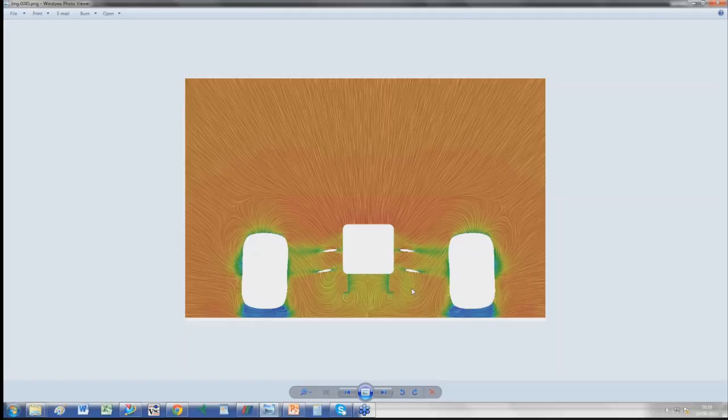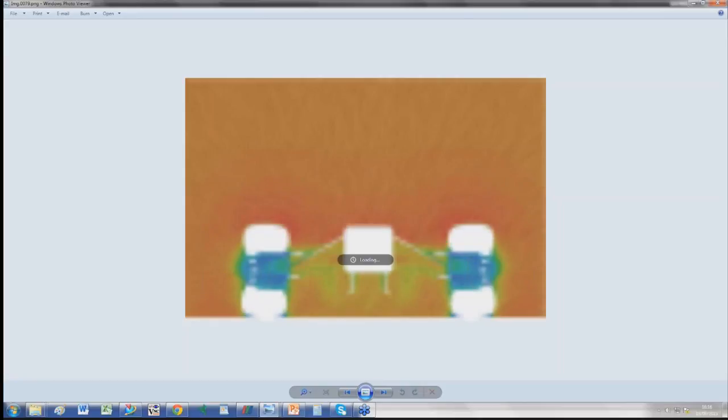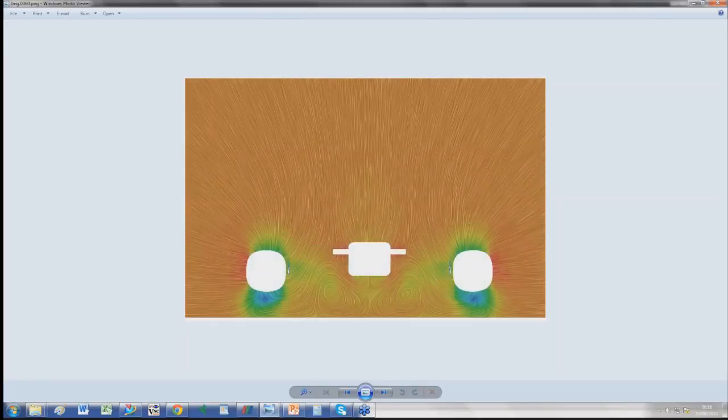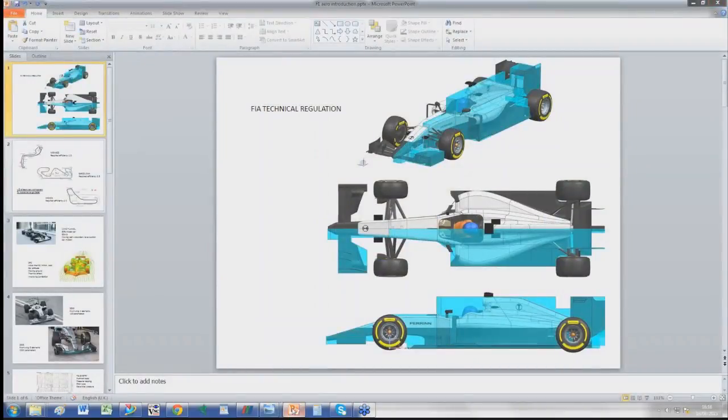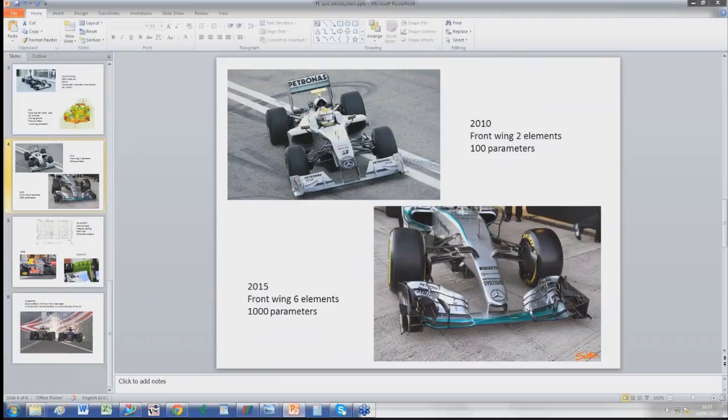to improve. And it's very clear that we need to develop the front wing much more to make this vortex stronger. It will mean that we need to crank or put more camber on the front wing in this area. So if I come back to my Mercedes comparison, it would mean that we need to do what they've done, which is put a lot of camber here, but that means making sure the flow is still attached, so maybe more elements, the same discussion, and that will mean the vortex will be much stronger and travel longer.